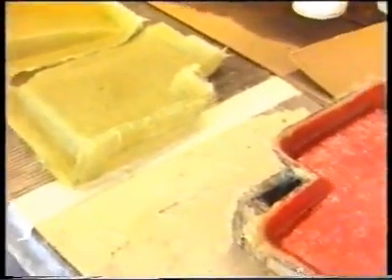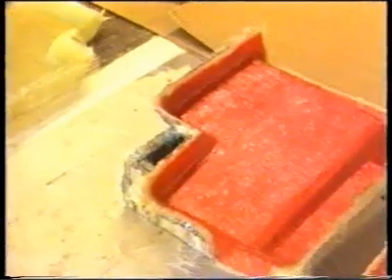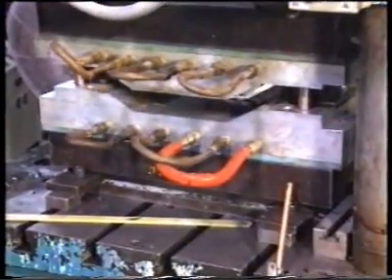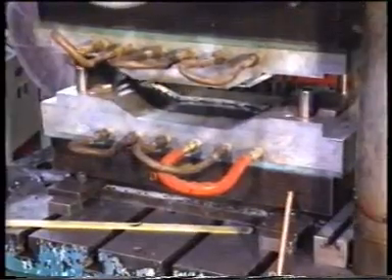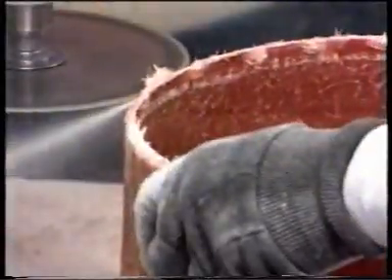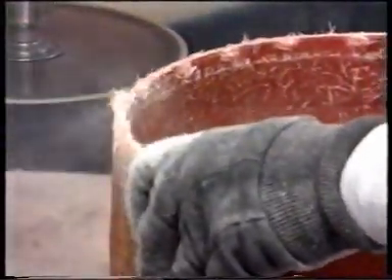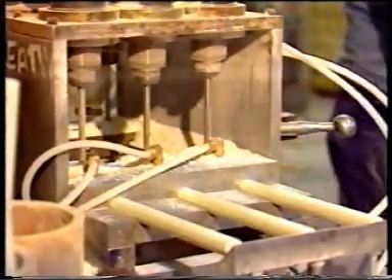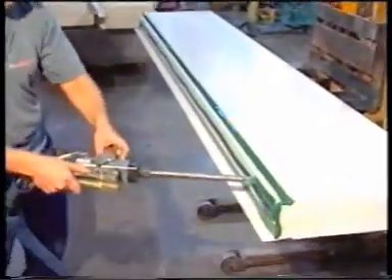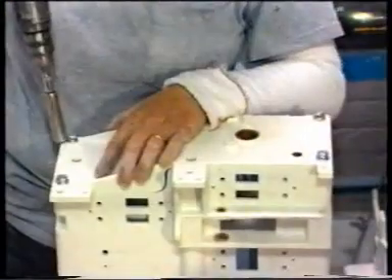After production, composite parts may be allowed to cure at room temperature or with open-air heat assist. Composite parts are also commonly consolidated and cured in heat platen presses, ovens, or autoclaves. After curing, composite parts can be cut, machined, drilled, and otherwise fabricated by many of the same methods used for metals. Additionally, composite parts may be joined and assembled using adhesive bonding and mechanical fastening.